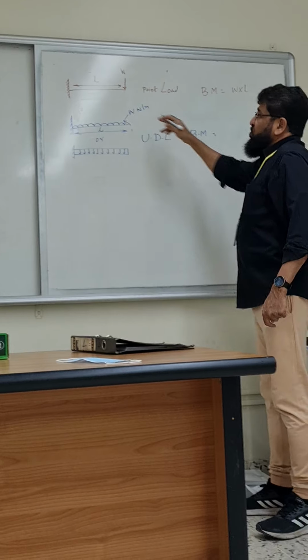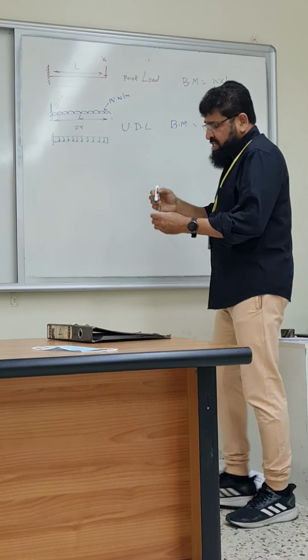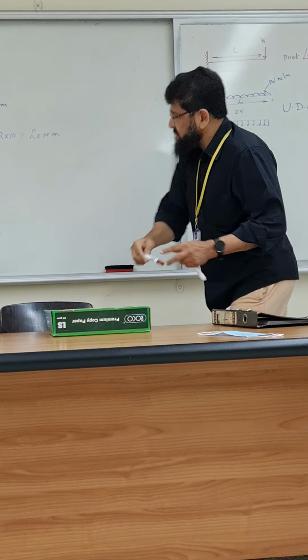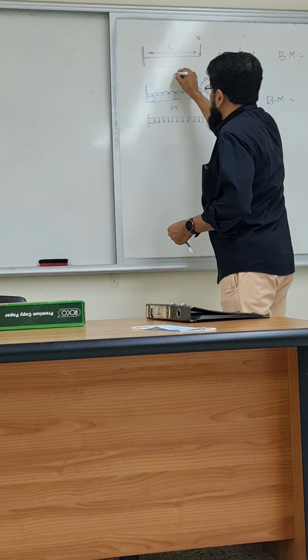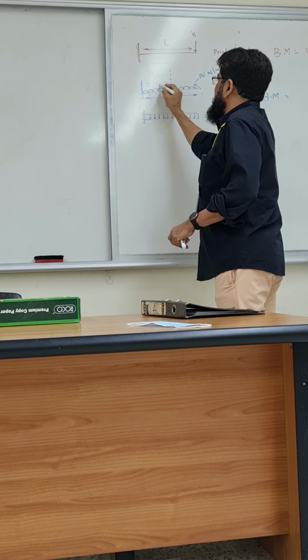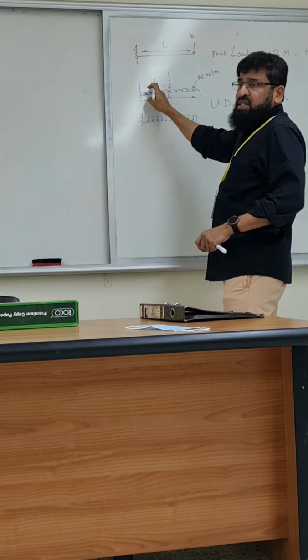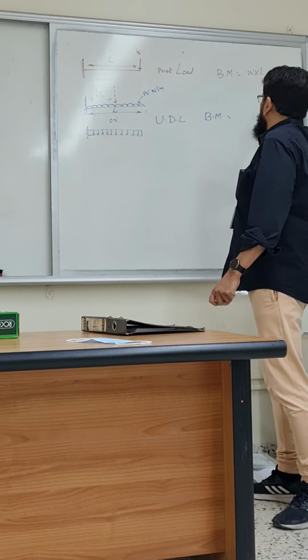Moment is what? Bending moment is force multiplied by perpendicular distance, isn't it? So where does this load act? This load acts exactly in the middle point, correct? As I said, right? What is this distance? L by 2. You agree with me? This is L, so it is L by 2, correct? L by 2